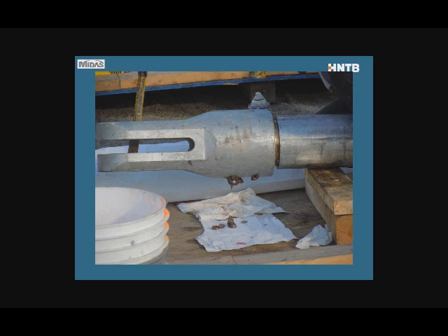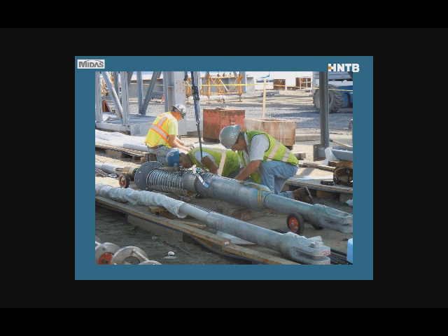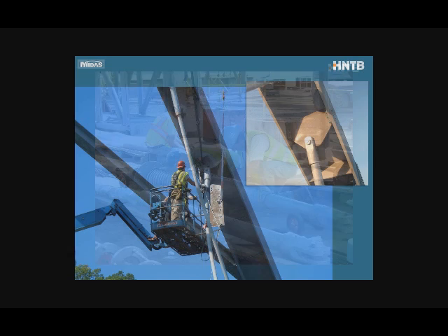So in this next picture, you can see it's been threaded on and filled with a corrosion inhibiting grease. And here's the assembled cable, actually 2 side by side. The one that's currently being picked up, that's a very short one near the ends of the arch rib. So you can see we have the pin, we have the anti-vandalism where that yellow sling is just long around, and then we have the rebar and the lower flange plate where it's connected to the tie girder. So this is a very tiny one. The one in the foreground is more typical, where you just see the upper anchorage.